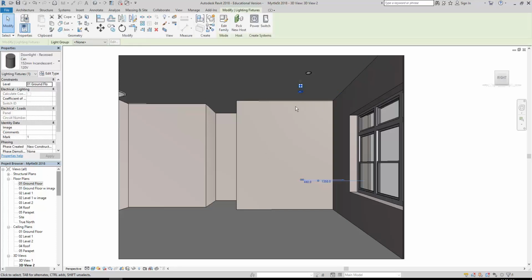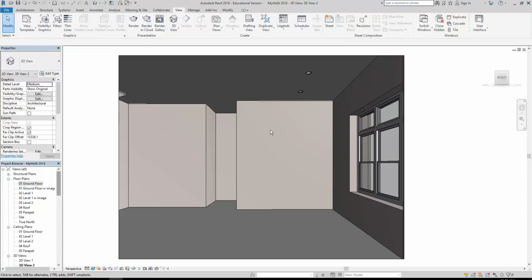It's the shape of the light. So in this case it's a cone, but it could be a sphere, or you can do them coming from a line. But that's why I don't want to show it to you now, because linear lights can be a bit harder with Revit, just because of a technical issue with rendering. Unfortunately, I know everyone wants to do strip lighting these days, and that's a good thing, but there are some technical issues with the way the rendering engine in Revit works with linear lights. So we'll come back to that, but otherwise those lighting families work really well.